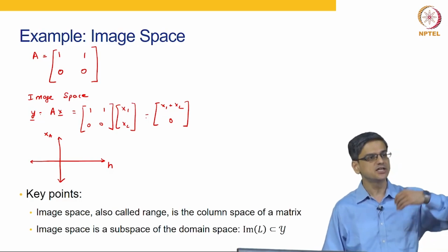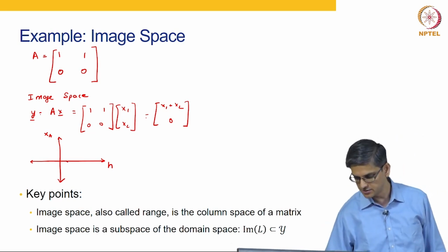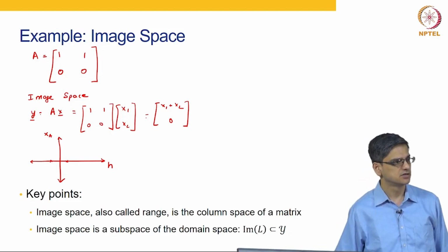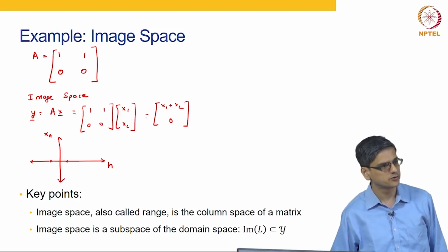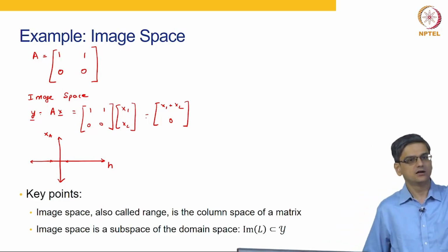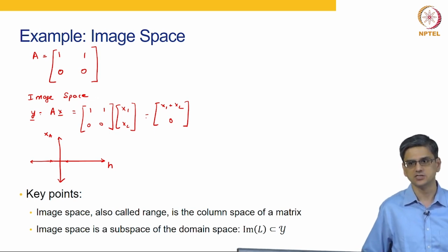Let us say you increase flow rate F1, you are going to increase the height. You decrease flow rate F1, you are going to decrease the height. You increase flow rate F2, you are going to increase the height. Let us say you increase the flow rate F1 by 10% and you decrease the flow rate F2 by 20%.